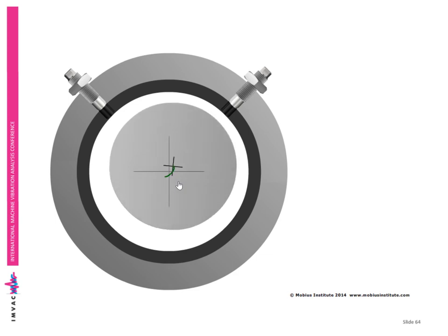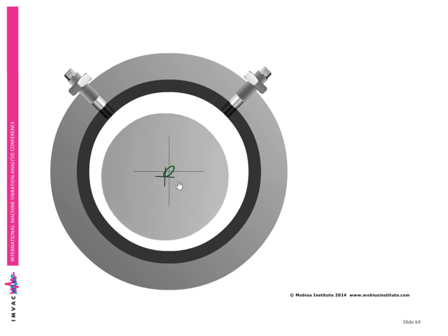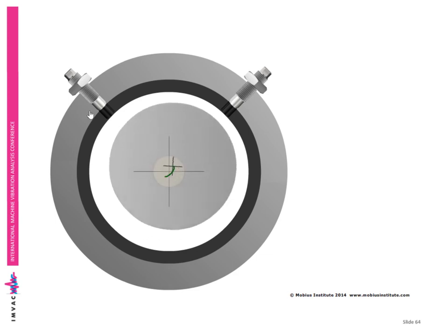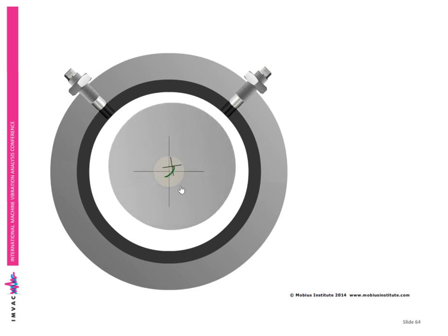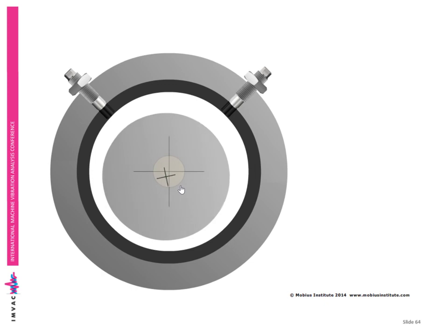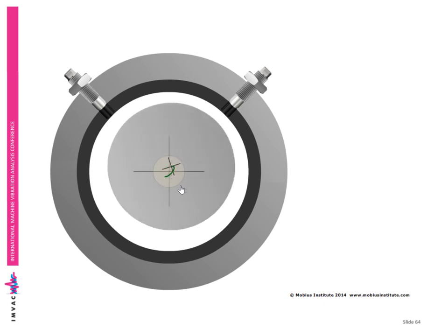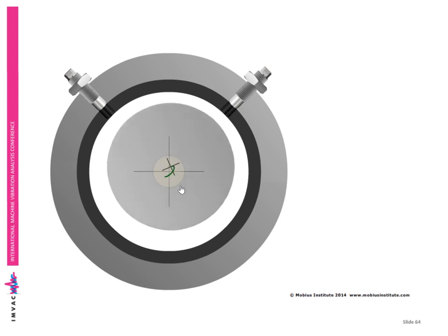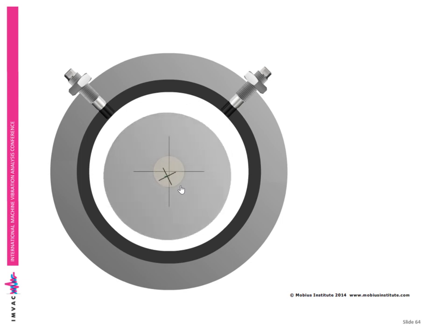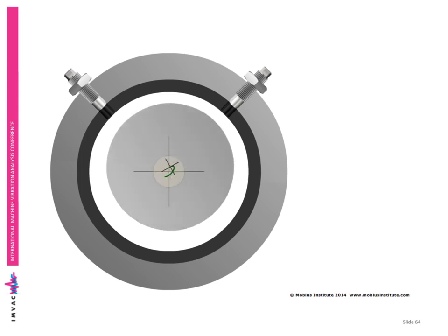The shaft, or the journal, can't move outside that bearing, and we represent that available clearance by this circle here. And what we're building up here is a plot that gives you an indication of where the center of the shaft is located within the bearing.